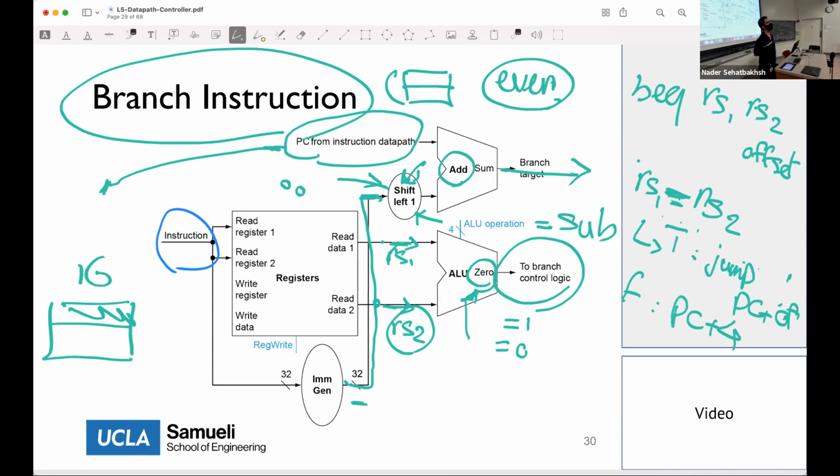Adding and subtracting, it could be that it's actually doing the add, but generally they are the same, because you have to go through all of the bits, and also anding has to go through all of the bits. So in terms of latency, it doesn't really matter. But what the subtract is actually doing inside the ALU could be anding or even adding with the negative value. So you basically negate and then add. That could also be another way that you do the subtract. Other questions?